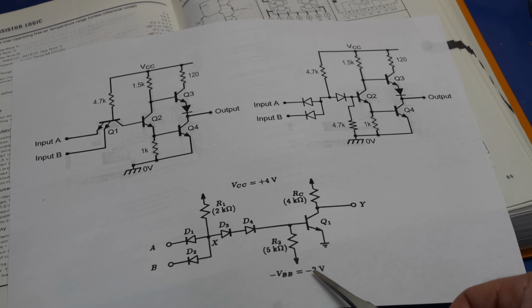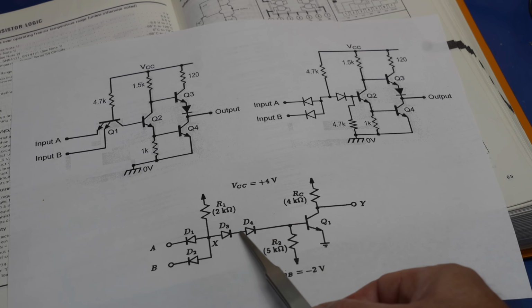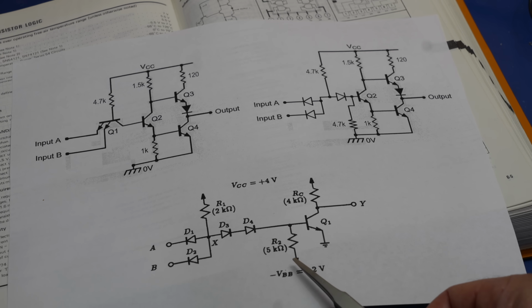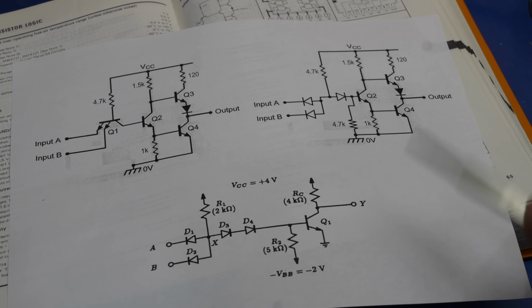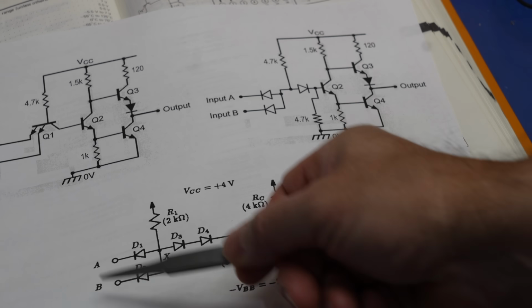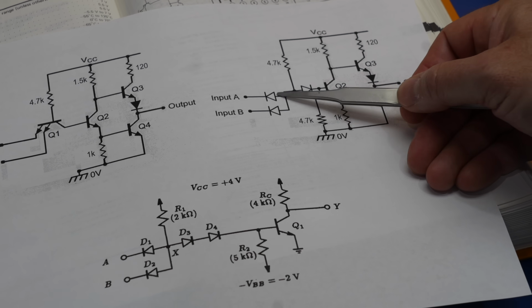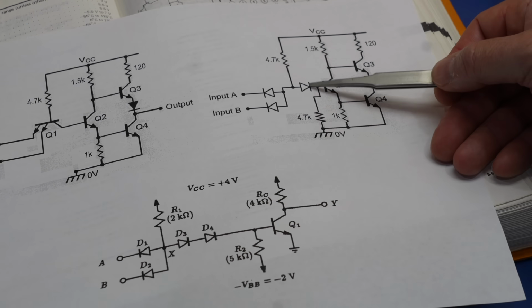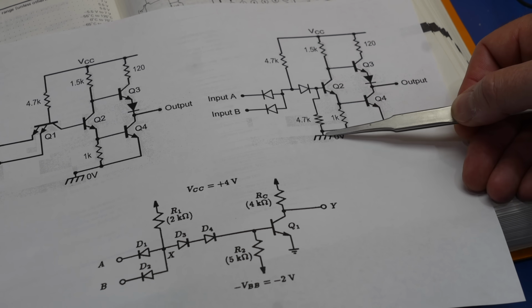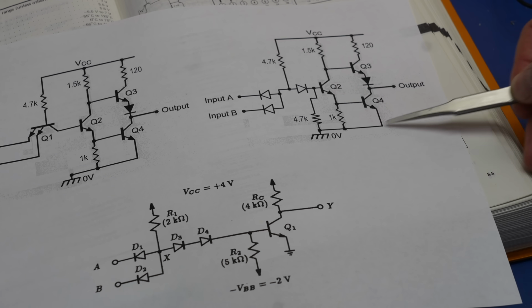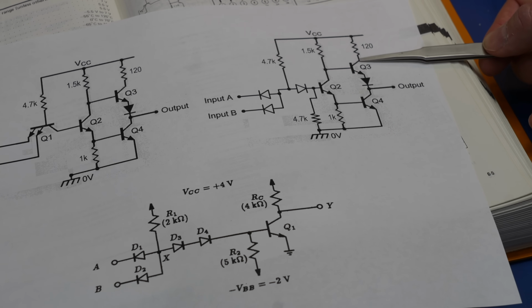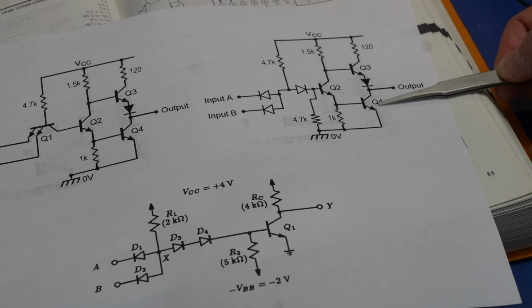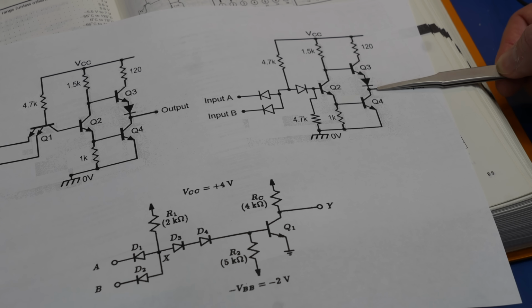Note that they use a negative voltage usually in DTL. That's for a side issue, because they never want D3 or D4 to stop conducting, so they don't have the penalty of the recovery. So instead they keep it conducting, but to a negative voltage, but we can ignore that. So I just converted this so it works out of a single voltage. So you see my 2-input diodes, I eliminated one of the diodes, so it is only 1 because I only grounded to 0 volt. I stuck it to the back of a TTL circuit, which is actually the same as here, except they put what's called a totem pole output to boost the fan out. So one output can drive a lot of inputs.